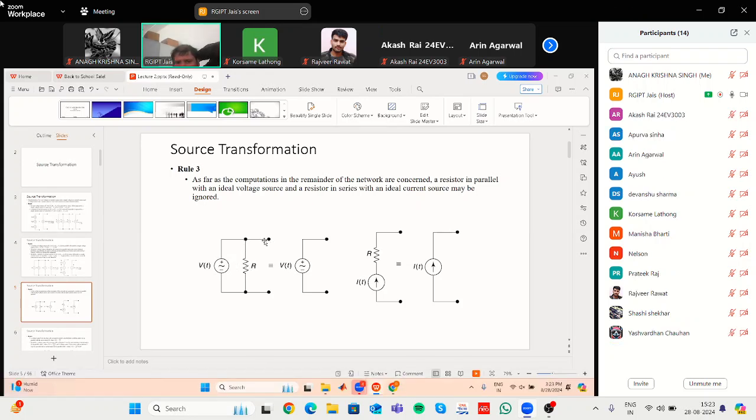because the same voltage will be applied to this terminal, which is of your interest, because you will be applying your own circuitry that needs some voltage to be connected across this. But this independent voltage source, by its very nature, will maintain the same voltage V across this terminal and this terminal. Then this resistance will not come into the picture. So you can remove the resistance, because it is of no use.